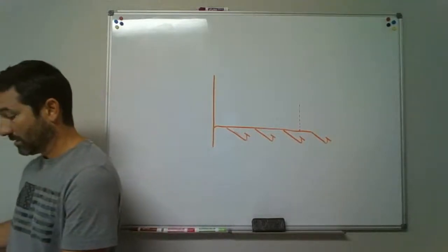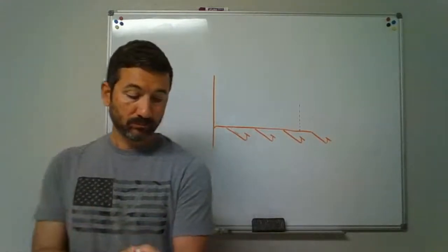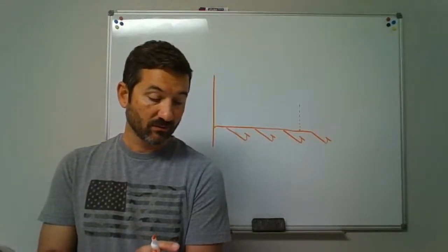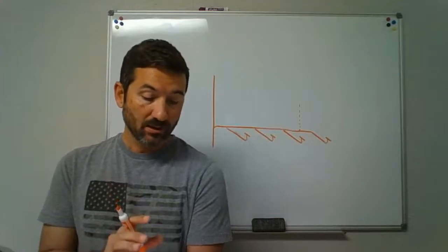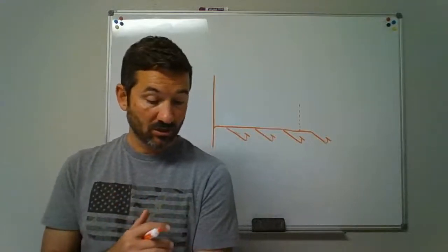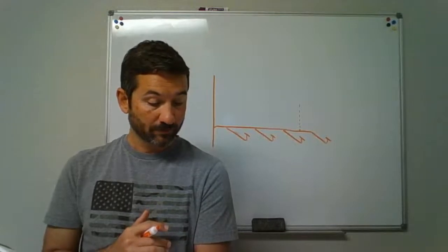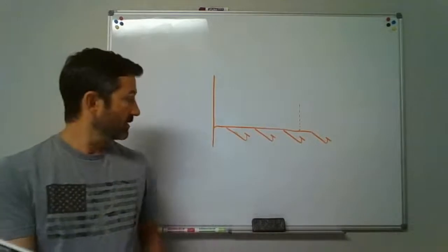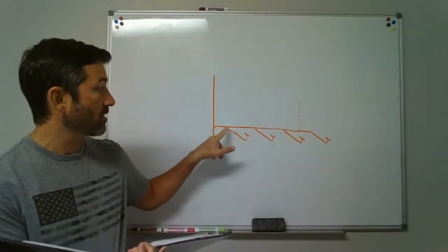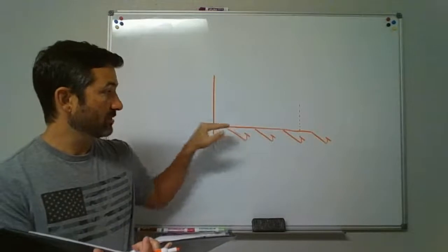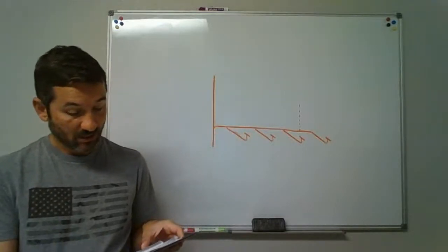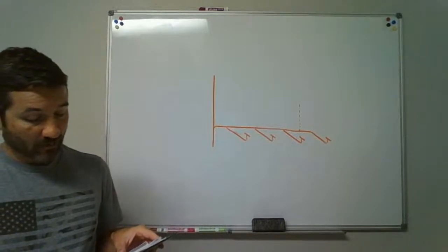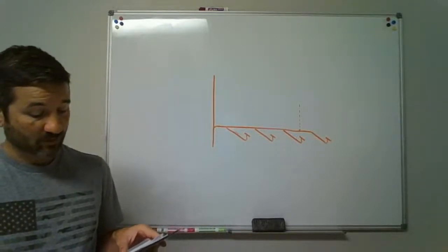Okay. Now let's read some rules and see where this information is coming from. 914.1 says the circuit vent is permitted a maximum of 8 fixtures that can be discharged into it. That's what we mentioned. Each fixture drain shall connect horizontally to the horizontal branch, so individually connected horizontally, running each one into this horizontal branch, into the fixture branch. The horizontal branch drain should be classified as a vent from the most downstream fixture drain connection to the most upstream fixture drain.